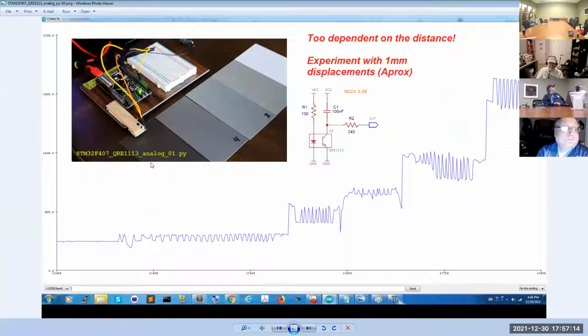Okay, this was an experiment with a sensor that is very tiny. Under this piece of wood, there is the sensor. This sensor used to have 100K in this position. So when the detector sees a white area, there will be a value about logic 1. But I changed the resistor for a capacitor, so now it is an integrator.